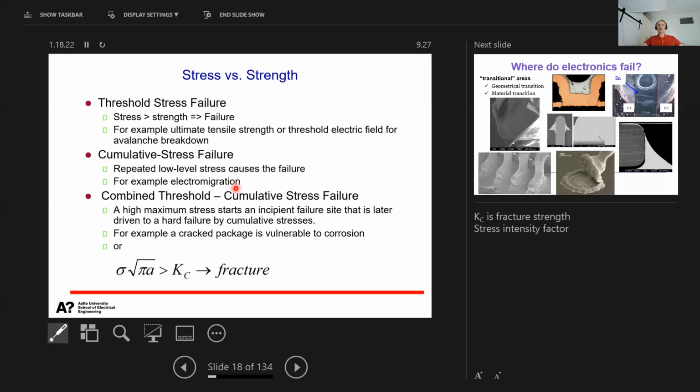So maybe that's not the best example, but let's say some other example could be that a corrosion or some electrochemical thing is affecting your sample. So you have, let's say, a carbon steel bar. You put it outside, it gets rusty. So the iron reacts with humidity, forms rust at the surface, and then you start bending it, so it withstands less stress when it's rusty than when it was new.